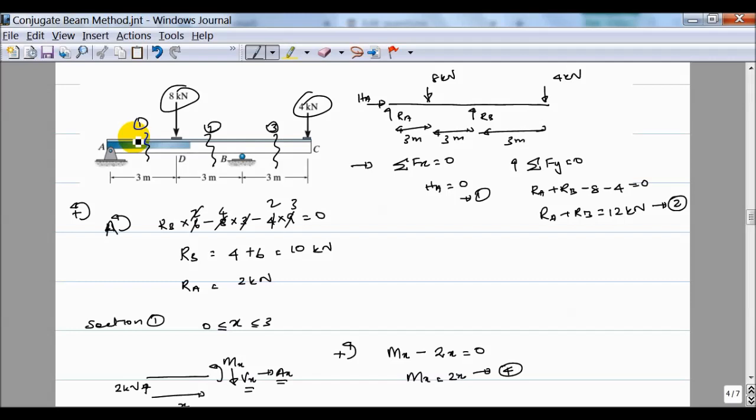If you want shear force and not bending moment somewhere inside a beam, then there should be a hinge. A hinge can carry shear force, but it cannot carry bending moment. If you consider point C in the real beam, that can have deflection and slope, which means in the conjugate beam there can be shear force and bending moment, so it should be a fixed support.